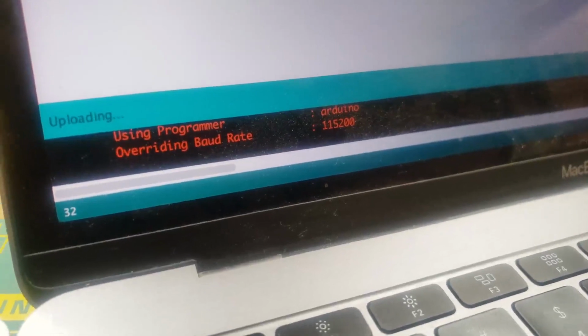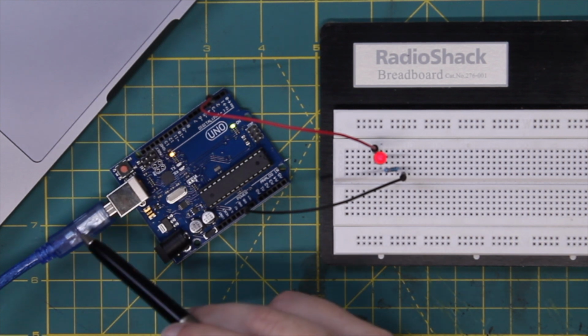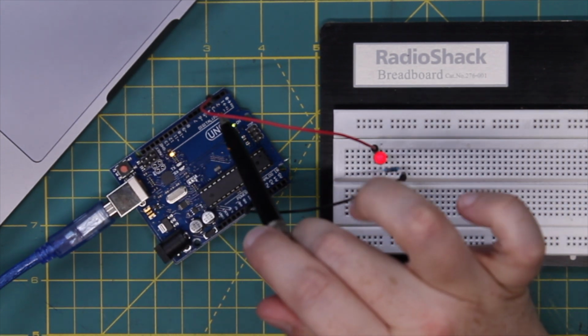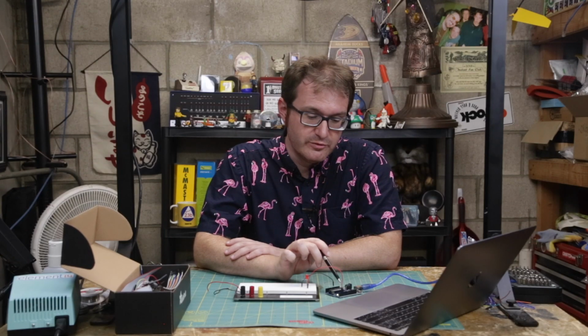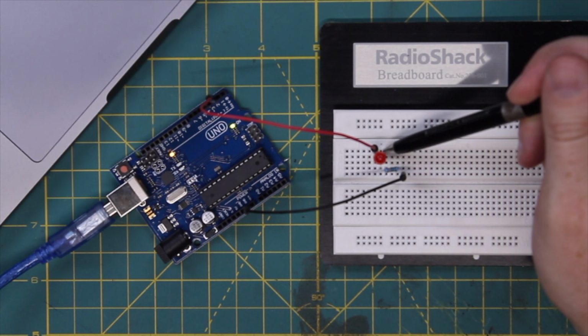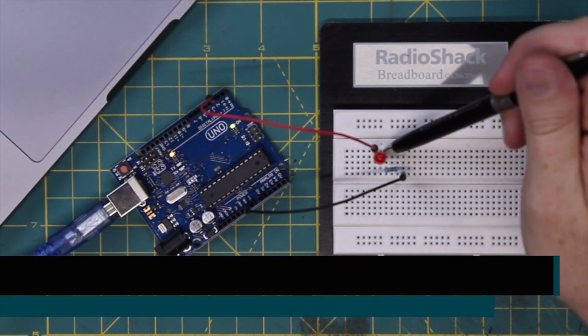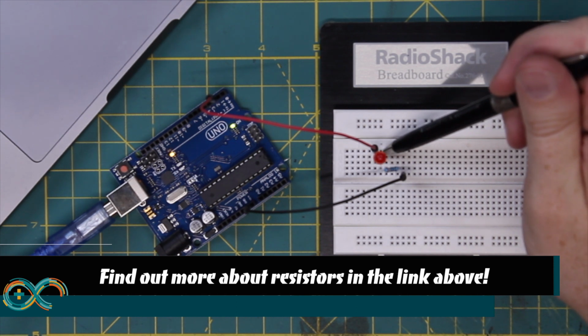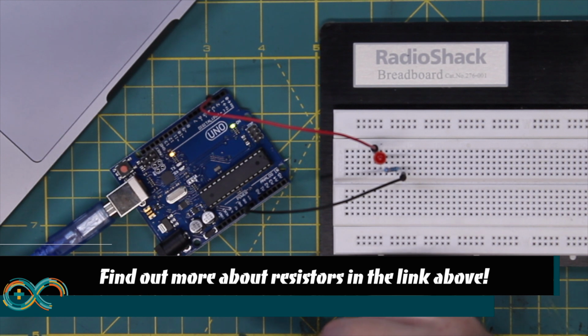Now that we know what the code does, let's put it on the board and see what happens. And here we have our completed project. Power comes in from the computer, out on pin 2 to our LED. The power is toggled on and off via the sketch. The LED goes on and off as the power is toggled. A current limiting resistor protects our LED, and the whole thing runs back to ground onto the Arduino.